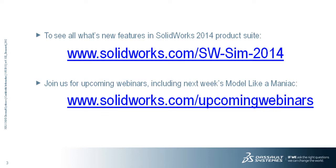There's a question here, Delphine. Is stress and fatigue of plastic parts incorporating creep? Okay, that's a very good question. When you do performance testing on plastic parts, they are usually made of what we call nonlinear materials. So to analyze the stress results on plastic parts, you will do what we call a nonlinear analysis, and yes, we can include creep when you define your material model. So this is something that you can do.